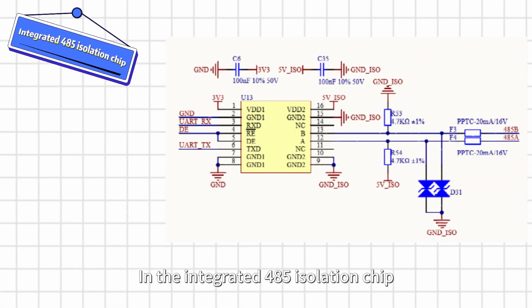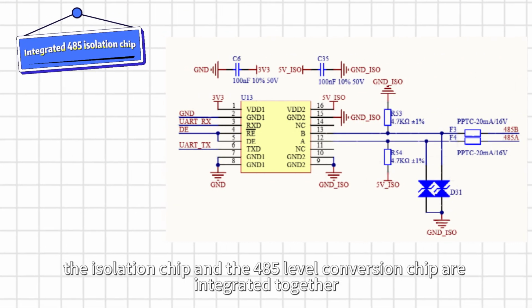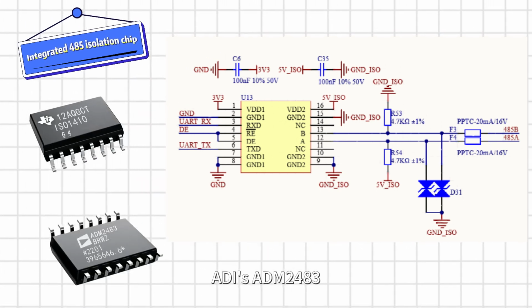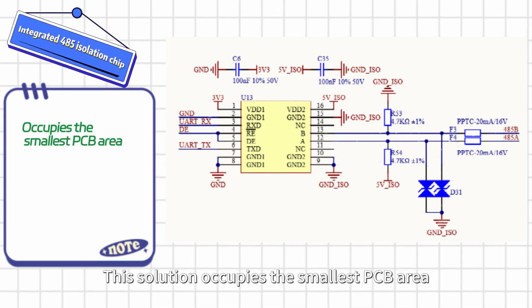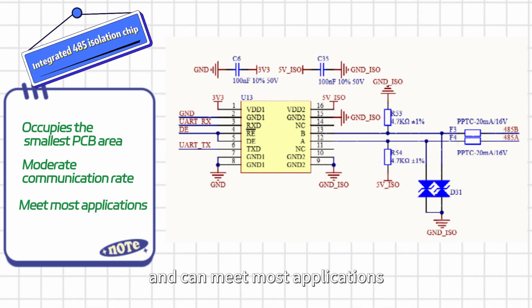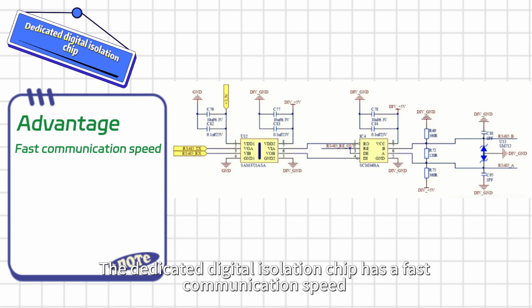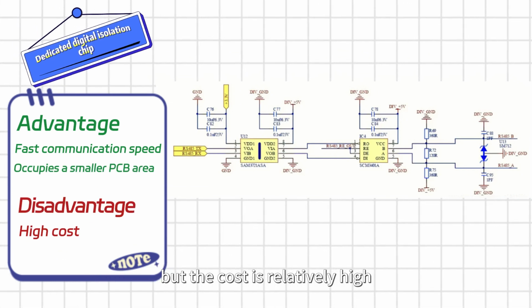In the integrated 485 isolation chip, the isolation chip and the 485 level conversion chip are integrated together, such as TI's ISO1410, ADI's ADM2483, etc. This solution occupies the smallest PCB area, has a moderate communication rate, and can meet most applications. The dedicated digital isolation chip has a fast communication speed and occupies a smaller PCB area than the optocoupler, but the cost is relatively high.